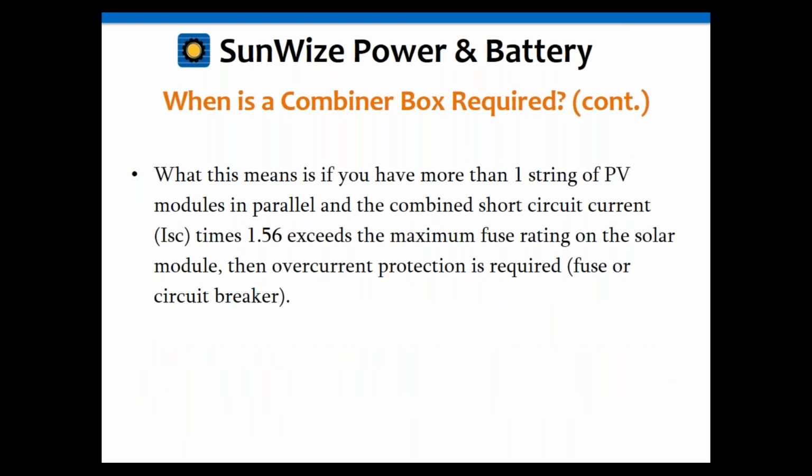Okay, now if you've got more than one string or module in parallel, do you need to have an additional circuit breaker or fuse or not? And this kind of gets back to that diagram at the very beginning with the terminology. It was showing one on each string, and in most cases you're going to need to have one. And basically what NEC also says is that